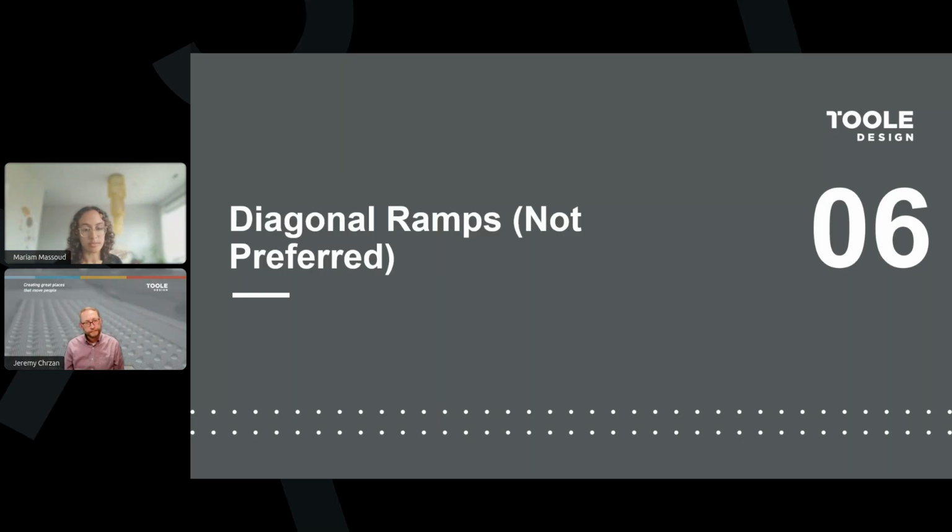Okay, we have a question from Christine, and she asked, is there a max distance from the point of curvature that a ramp can be placed? There's not a max distance, but particularly if you have an intersection with a large radius, if you are trying to locate your crosswalk as a perpendicular ramp on the tangent, inevitably that crossing distance is going to be so far from the intersecting roadway that the pedestrian is not going to be visible to the crossing